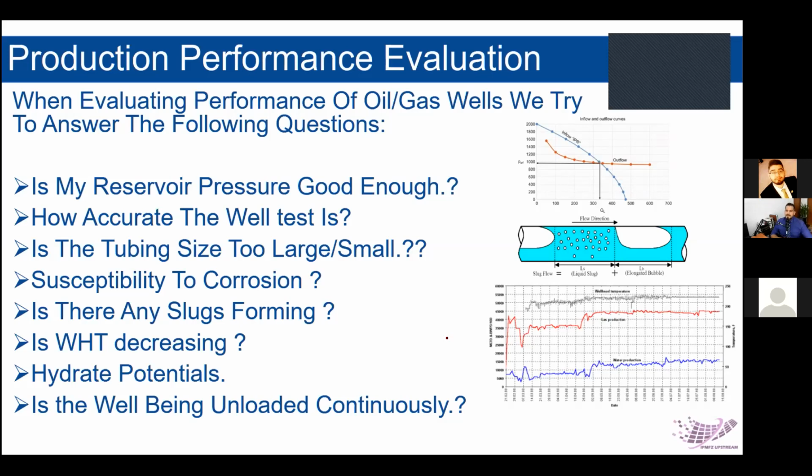So it was accumulating at the bottom of the well, and it finally made the well die. And actually, the solution to that is very simple. You can do it in an Excel sheet. It's related to the tubing size. You need to make your tubing smaller, so it will have less cross-sectional area and thus much higher velocity that will unload your well.